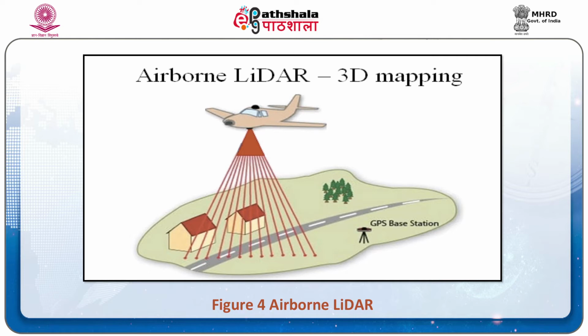The initial LIDAR data can be further enhanced using additional post-processing, some of which can be automated and some manual. Further processing utilizes the multiple return signals from each laser pulse. By evaluating the time difference between the multiple return signals, the post-processing system can differentiate between buildings and other structures, vegetation and the ground surfaces. The process is used to remove surface features to produce the Earth model, the DTM. It is also possible to do selective feature extraction, for example, the removal of trees and other vegetation to leave just the buildings, as shown in figure number 4.